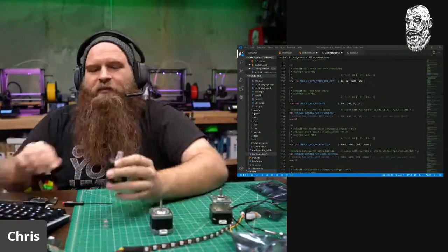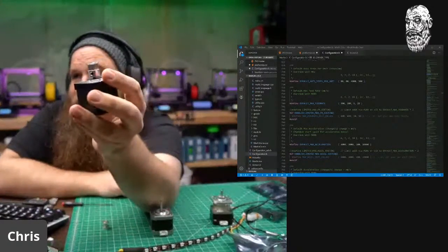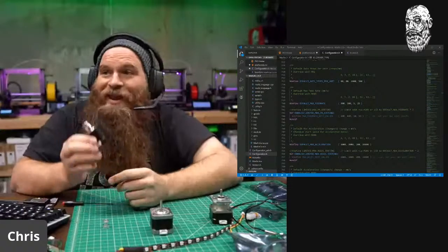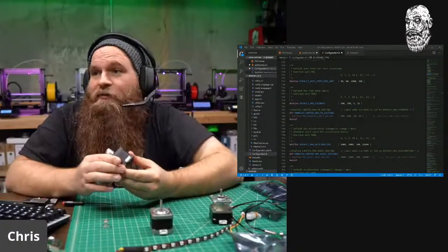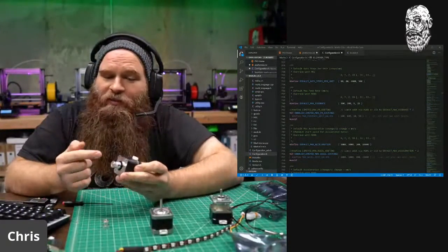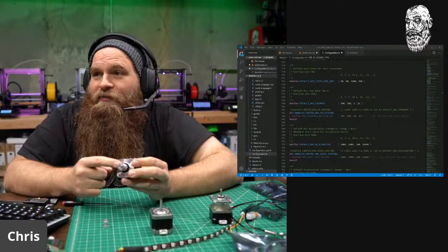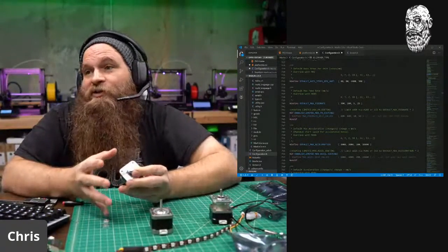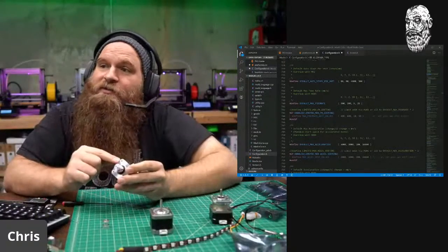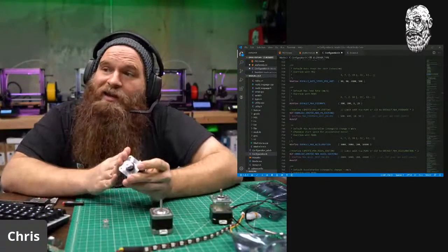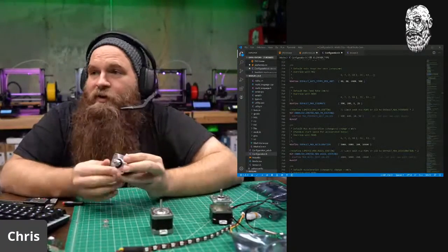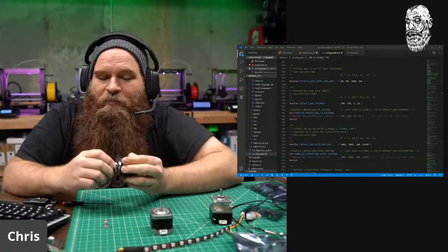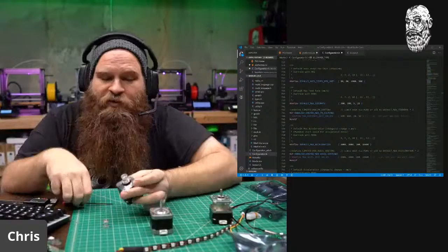So you have one of these fatter ones, and it's 12 millimeters on the teeth, ish. You have an 80 step per millimeter movement. Again, the larger this gets, the less resolution you get. So the steps per millimeter is just resolution. It's how many steps it takes to move a millimeter. It takes 80 steps to move 1 millimeter with this 20-tooth pulley on this 1.8 degree motor.